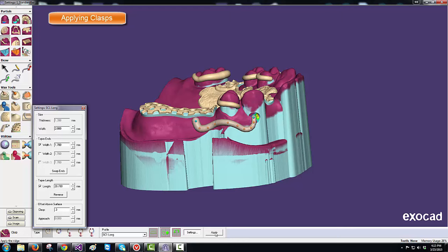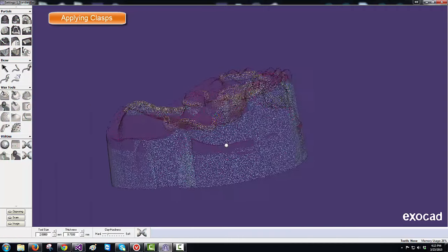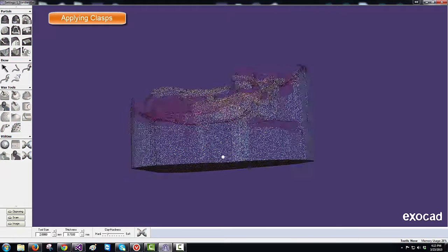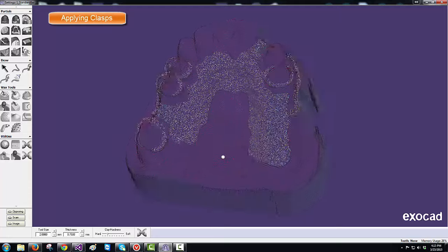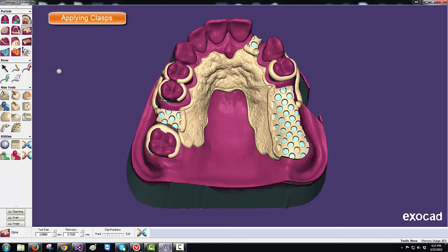That will be accomplished with the clone tool, your waxing tool. And you could set that to about 0.75 and sneak in behind the arm and apply wax to touch the tooth. And we'll smooth that in later. So when you do rotate, the model does pixelate. We're going to stay in that clone tool, but we'll adjust the thickness.